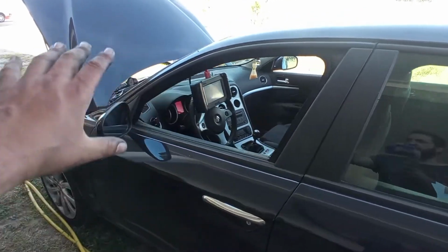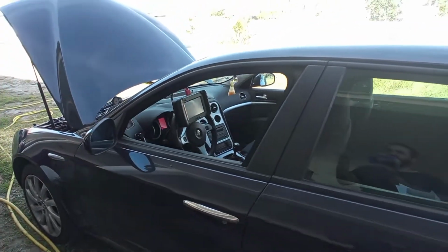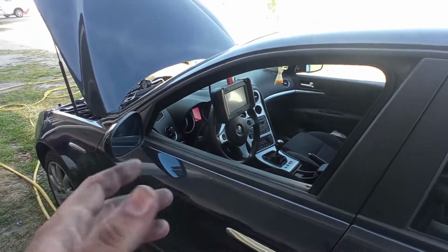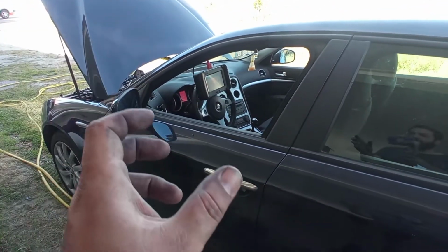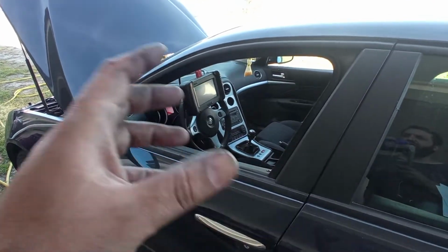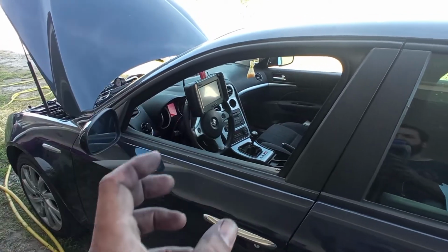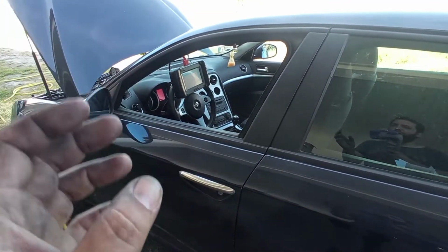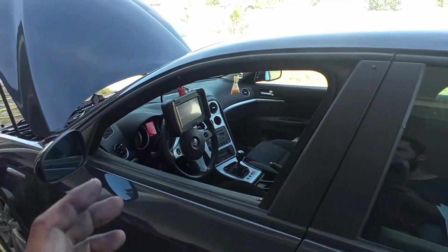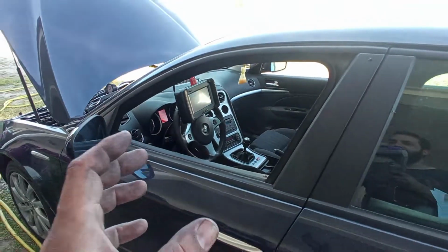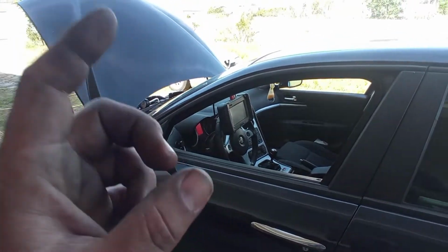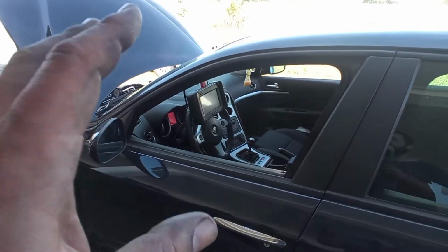I just put here a new DPF, everything is okay, the car does 300 or 400 kilometers between regens, and when you read the percentage once the car is, let's say, at 250 or 300 kilometers, the percentage will be near 100% clogged DPF. That does not state the condition of the DPF, it just states that it's almost time to do a new regen. It does not mean that it's time to replace it.